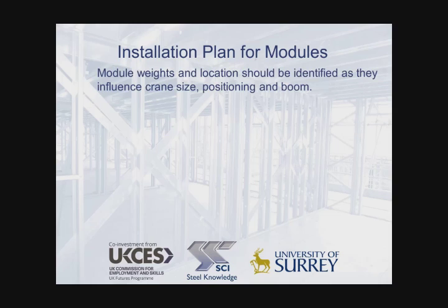It's important that a lifting plan for the modular installation is agreed at the very early stage of the project, and this should include module weights and location, as they influence the crane size, the positioning of the crane and its boom length.